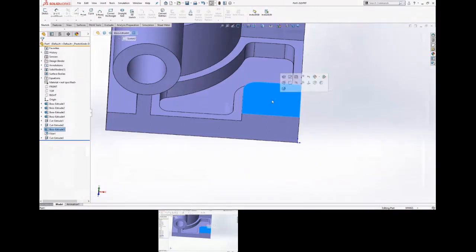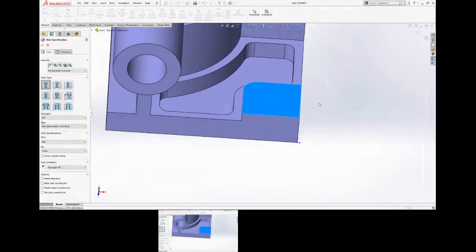So I click on this surface. I pre-select it on purpose so that when I launch the tool and I position it, I'm not in a 3D sketch. I don't know too many people other than people doing weldments that use 3D sketches, but it can put things in weird spots and at weird angles if you select things kind of strange. So a trick for hole wizard: if you pre-select that and then launch the hole wizard tool, which I have right here, it's going to put that location sketch on that face. Right. So just kind of a handy way to do it.